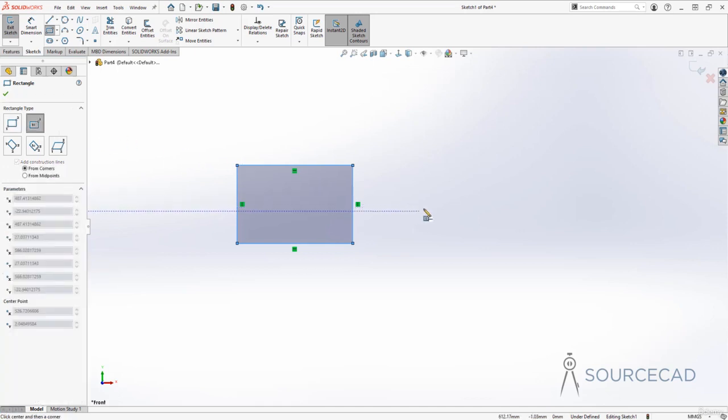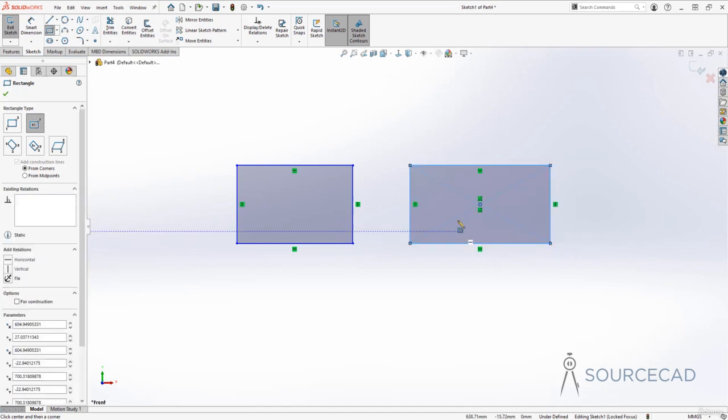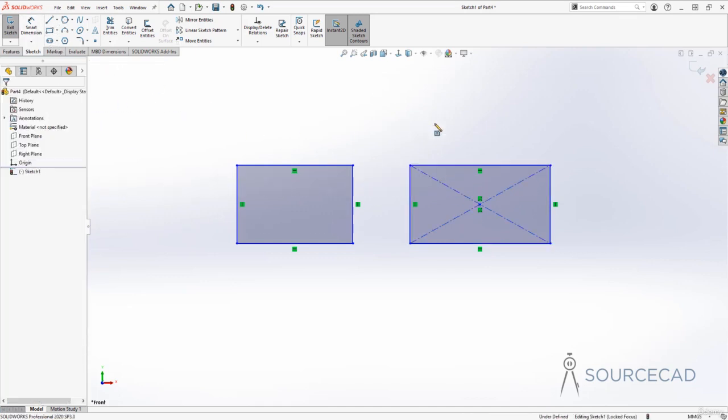and then I'll click at a point, and that point will be the center of rectangle. Now if I move out, you'll see that we now have two diagonals, and also the rectangle will be made accordingly. Now the advantage of this rectangle is, well, very basic. In this case, you can use these diagonals as references, and you can even dimension them later using the Smart Dimension tool. All right, let's press escape. Let's see what we have next.